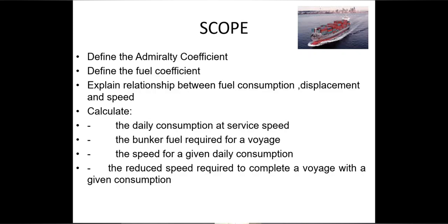For a particular voyage, how much bunkers will be required? Because the stemming of bunkers is based on this calculation, and then accordingly we intimate to our owners or charterers that this is the bunker requirement. So we'll calculate under different examples the bunkers required for a voyage.